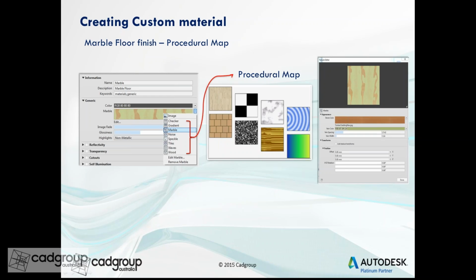In the diffuse surface area, you can apply colors, or you can apply map types. If we use color information, that is just a color, but you can use a map, and maps have different types. Most people use a map type called image, which allows you to browse any of the image files, like JPG, TIFF, TGA, or BMP formats, to apply directly on the diffuse surface area.